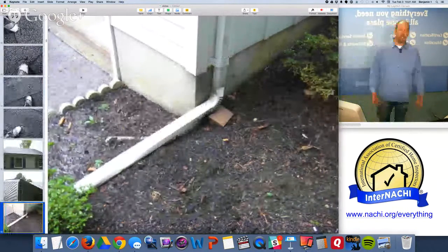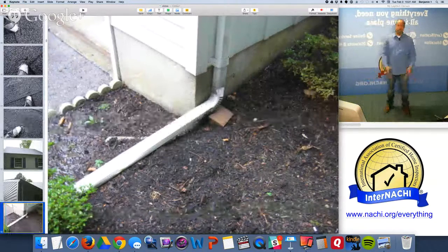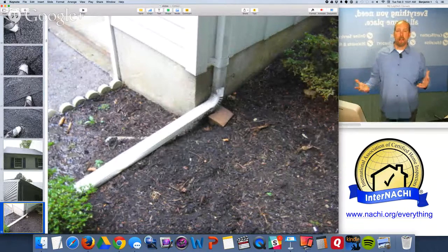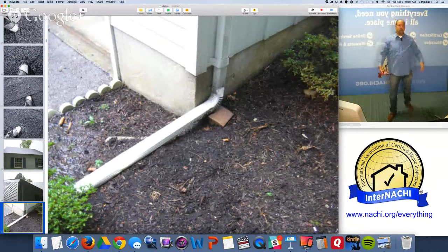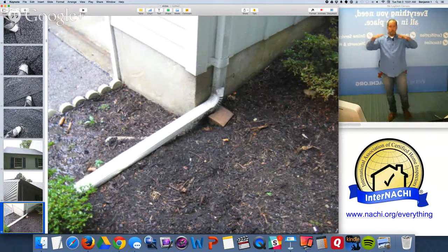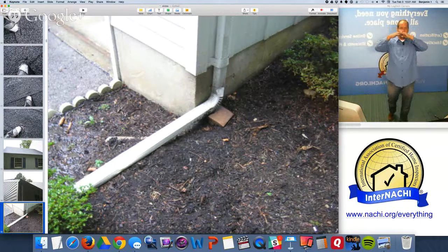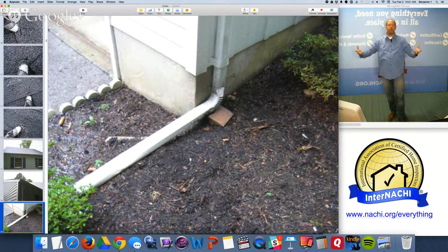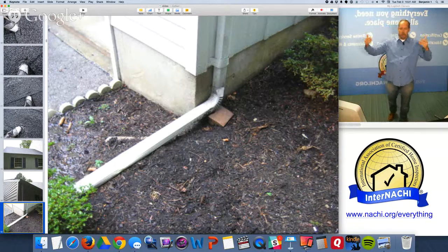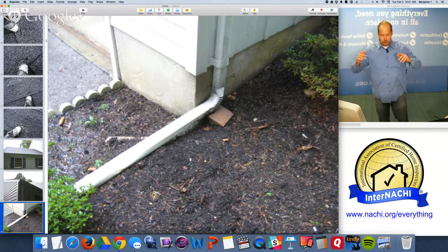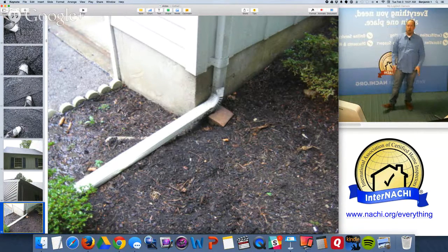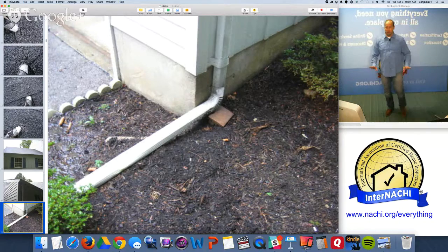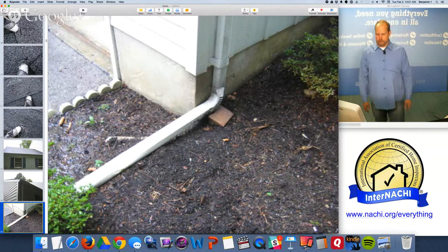Downspouts. Imagine it just rained at this inspection, so water is on my mind. But on a dry day, you kind of forget. Everything looks great. But you have to imagine how water falls upon a building. It hits the top, obviously, slopes down. Even a flat roof has some slope, so it's moving. It's caught, or maybe not caught, by gutters. Gutters directed to the downspouts. Downspouts direct hundreds of gallons of water, for a typical rainstorm. It's got to divert all that water away from the foundation.